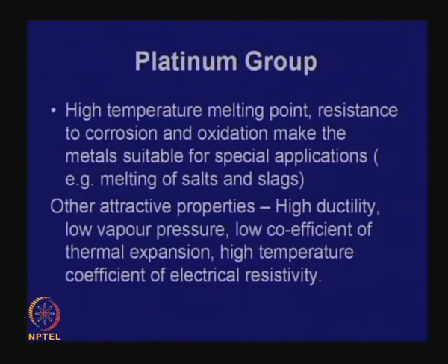So, if you have platinum vessels, platinum wares, or platinum thermocouples, platinum rhodium things, it has to only go back to 1 or 2 designated companies which make things out of platinum. So, platinum, rhodium and platinum group metals do not have this easy resale value as gold and silver have, although they are far more expensive. Now, platinum group metals have utility value. They have high temperature melting point, resistance to corrosion and oxidation, and these make the metals suitable for special applications.